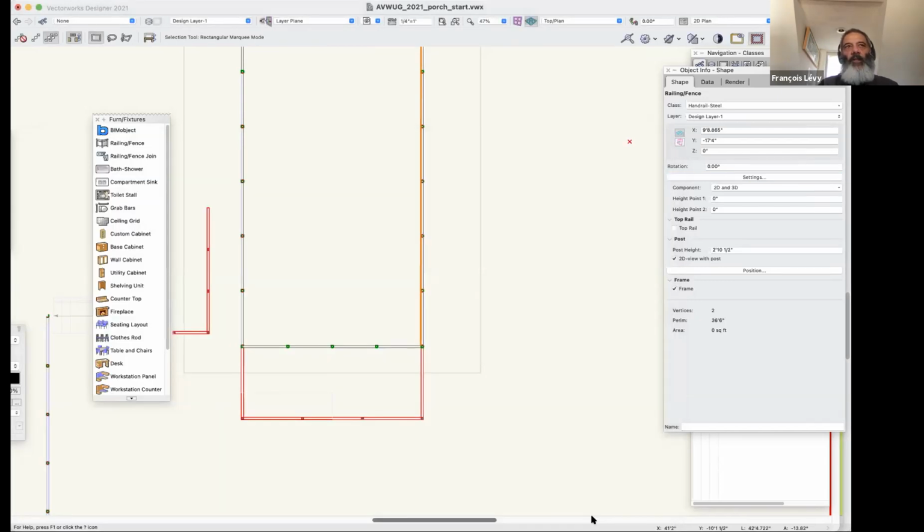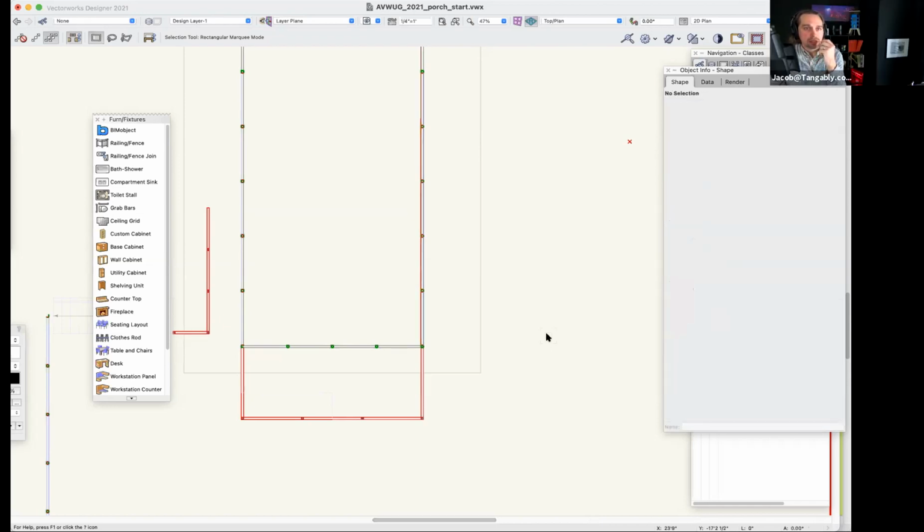If you wanted something fancier than 45, then you would want to use something called a surface array in order to simulate that. And then you'd have a tremendous amount of design control over it. But surface arrays are computationally a little bit heavier duty. They might be a little boggy to render if you had a very complex or large model with large extents. It seems like the default would just be to go back to a texture in that circumstance, because then you're unlimited.